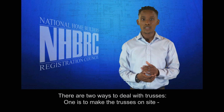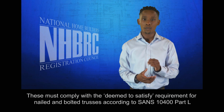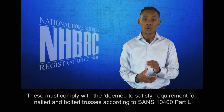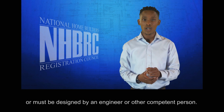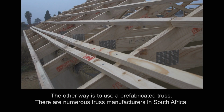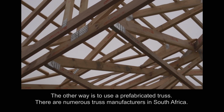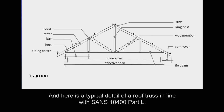There are two ways to deal with trusses. One is to make the trusses on-site. These must comply with the deemed to satisfy requirement for nailed and bolted trusses according to SANS 10400 Part L, or must be designed by an engineer or other competent person. The other way is to use a prefabricated truss. There are numerous truss manufacturers in South Africa. This is an image of a typical engineered truss, nail-plated. And here's a typical detail of a roof truss in line with SANS 10400 Part L.